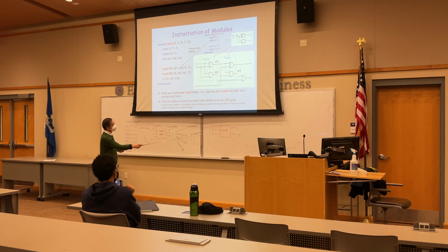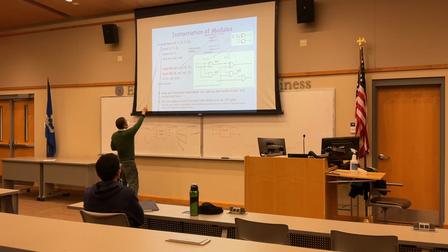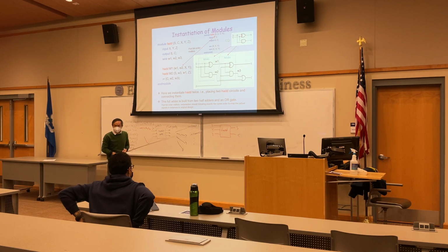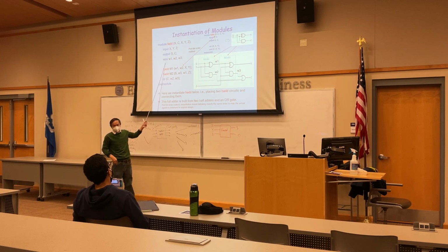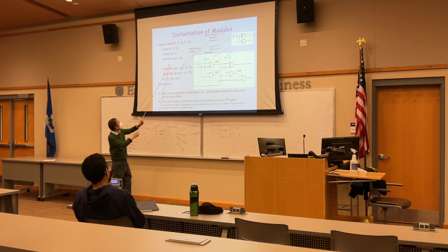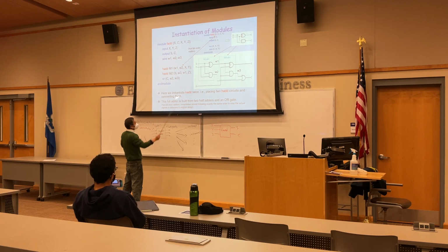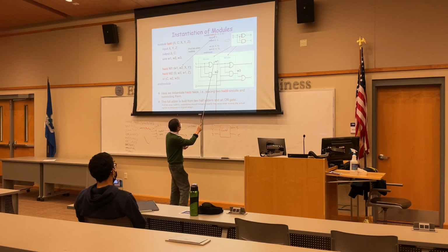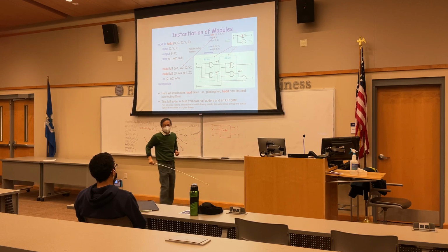Again, first declare the module, the module name, and the port list, S, C, X, Y, Z, and define the ports' directions. Input X, Y, Z, output S, C, but you have internal wires W1, W2, WC.